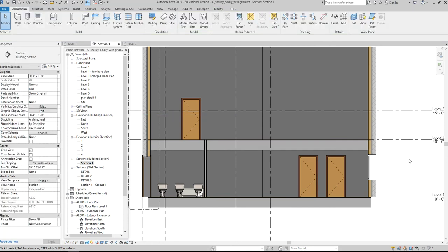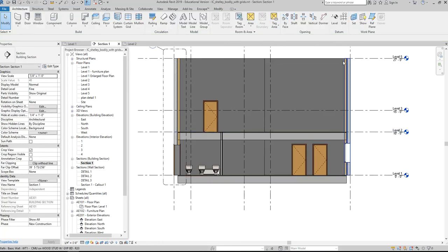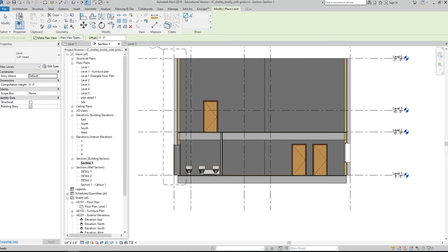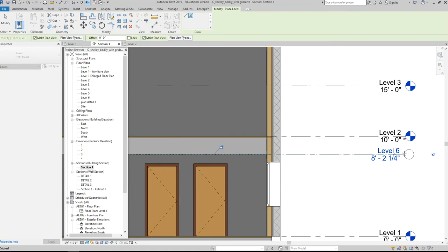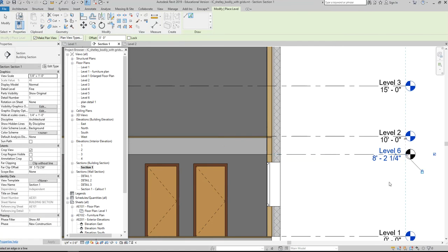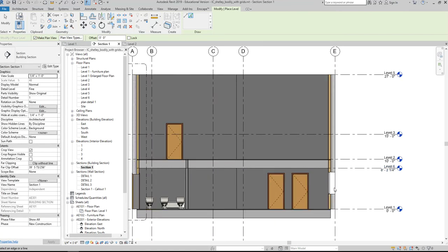Okay. So I'm going to create a couple of new levels here. This is a good review. Level, LL. And I'm going to use my pick tool to create it. Click. And usually I generate these before I get very far in the project, right? In the beginning of the project, I'm assuming a lot. I'm assuming I have these specific levels, and I'm also kind of guessing at the depth of my structure at that point, right? 12 inches, 14 inches, is it a slab?